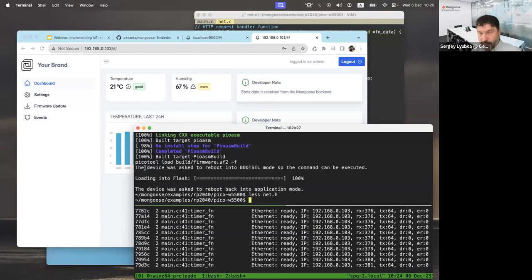That works nicely, because the thing that handles the connections could be a powerful internet server with a lot of resources, with protection you could put in place. And your way less powerful embedded device is just a client. It does not expose any network port, so it's pretty safe from the security point of view. It just makes an outbound connection to the remote server.